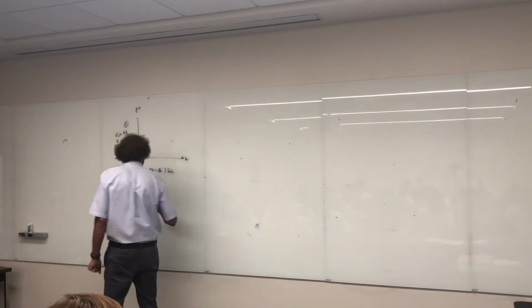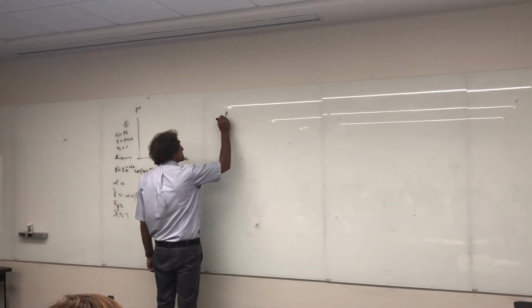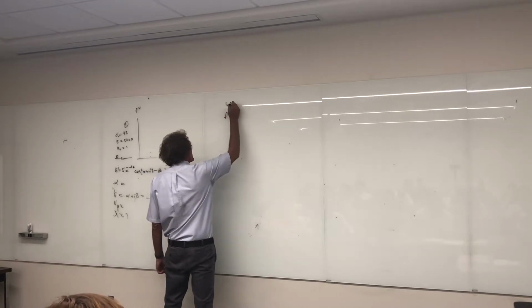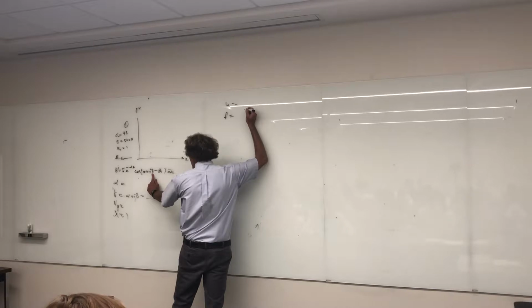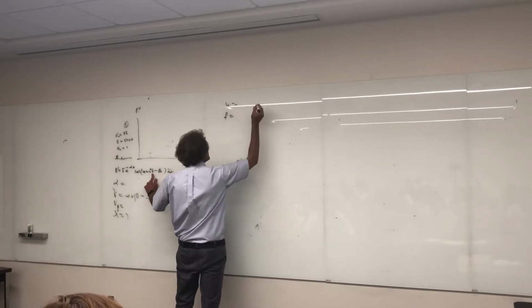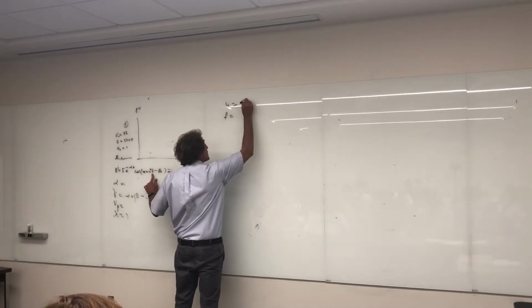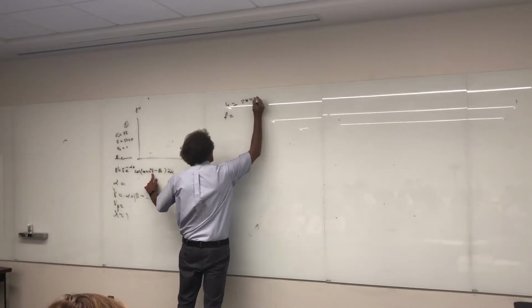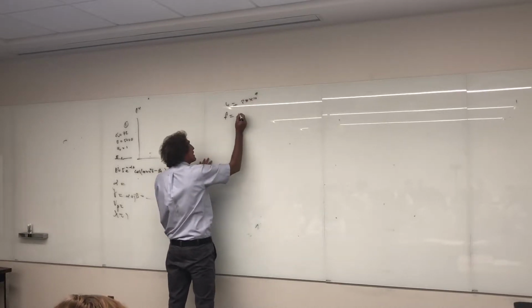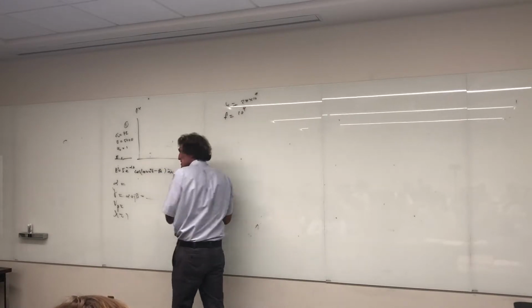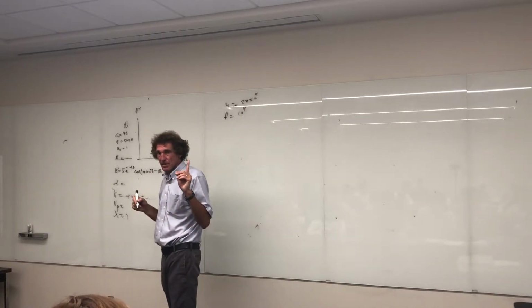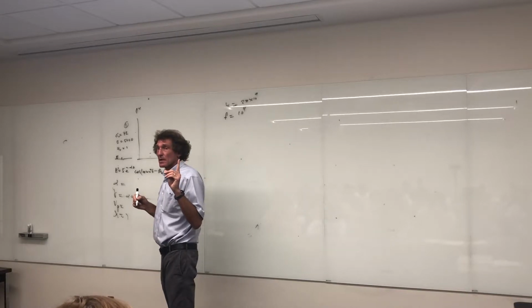First thing you're going to do is find the frequency. What is f and what is omega? Omega is always the coefficient of t inside the cosine, correct? It's 2 pi times 10 to the 9th. Now, what does that make f? Automatically, 10 to the 9th hertz. So you identify that. Everybody agree?